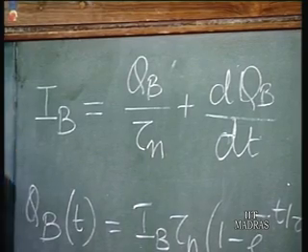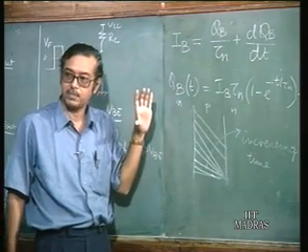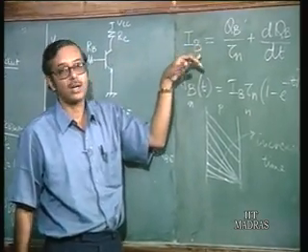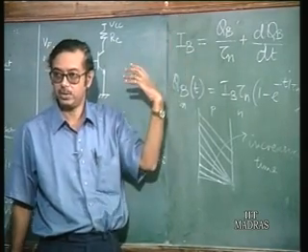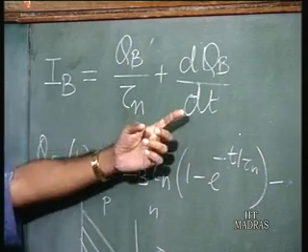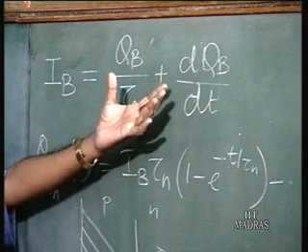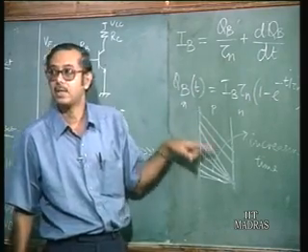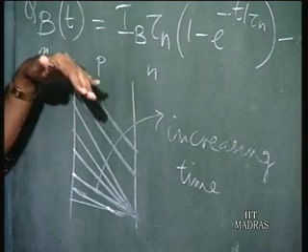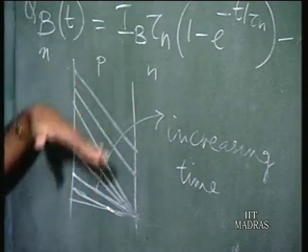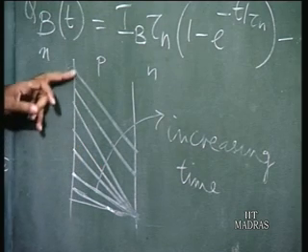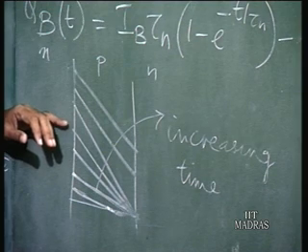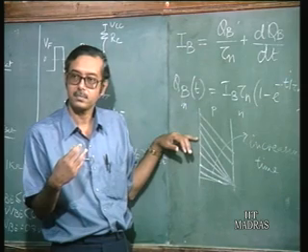All right. So, the base current now becomes, see, another thing you must remember from what we have discussed in the case of the diode, the base emitter voltage cannot change instantaneously. You have a lot of base charge. Now, according to this relation, the base charge is going to reduce because this has become negative. dq dt becomes negative also, but it will take some time. So, again if you go back to this figure here, which gives the charge profile, the charge profile which had built up is going to again go down, and as it goes down, the base emitter voltage is going to reduce, but it will take some time.